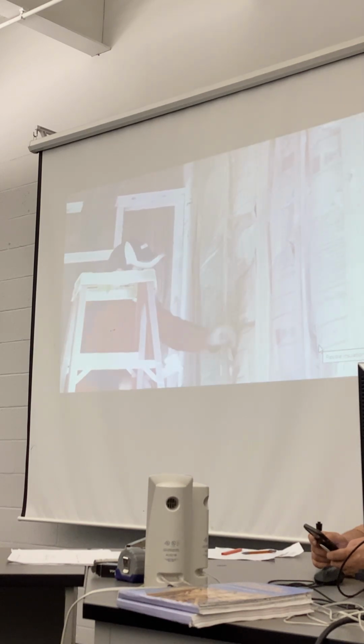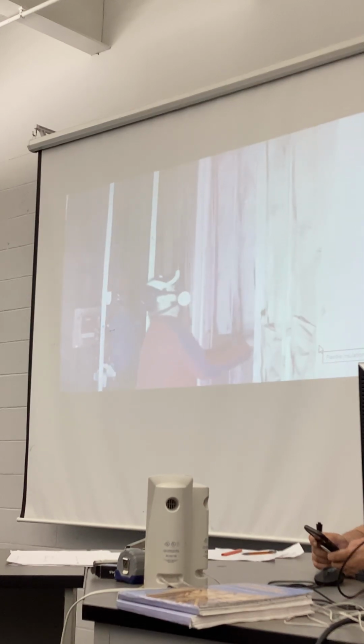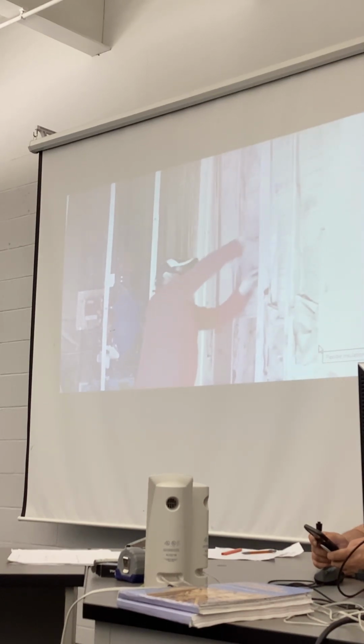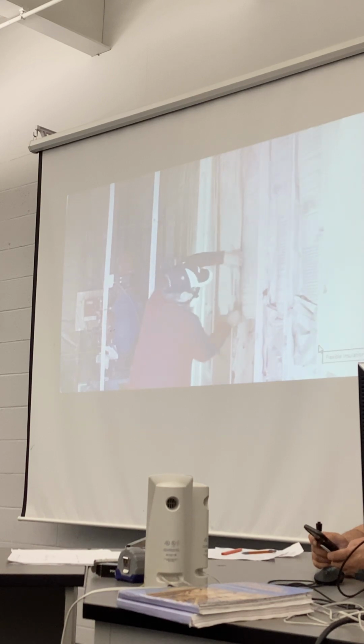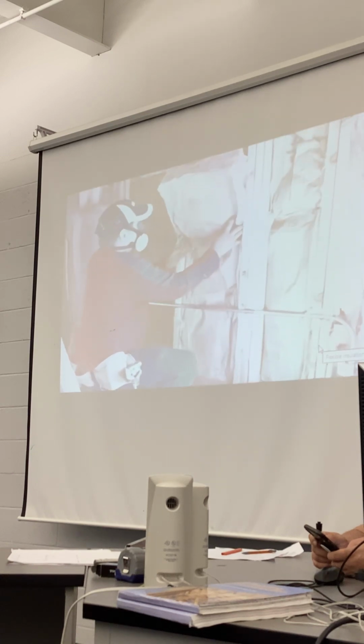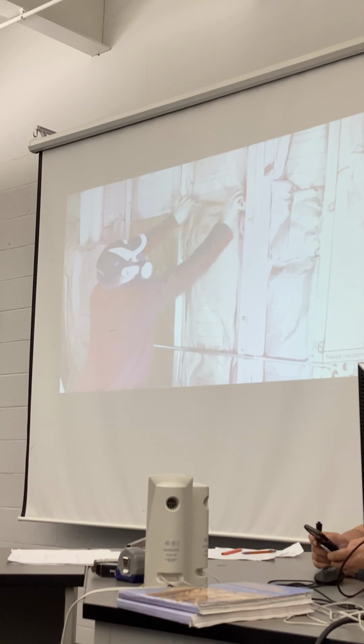Either method is acceptable. Staple the edges of the paper to the studs, starting at the top and working your way down. Spread the insulation blanket out smooth as you staple down the edges. If the roll is too short, butt another piece up against the first and staple it in place.